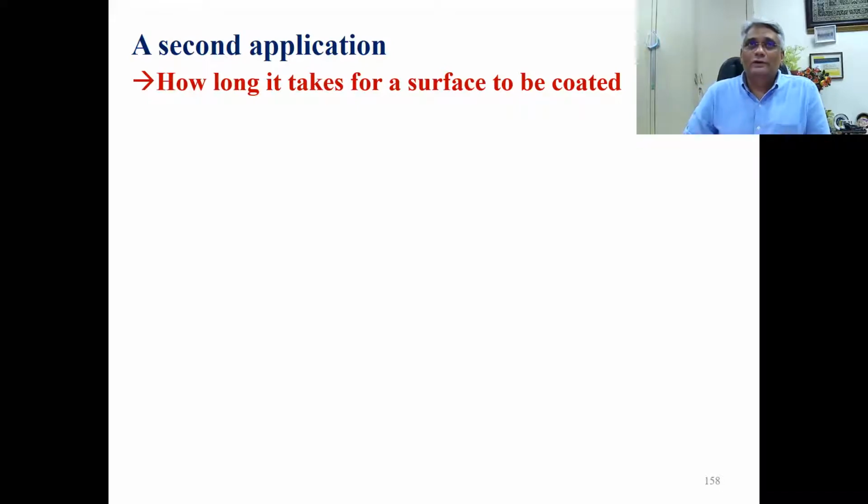But what you need to know is, even if you think you've cleaned the surface, how long it takes for a surface to be coated. Coated in the sense that it need not be a coating during the thin film growth process, even otherwise. What I mean by coating is contamination. If you think it's a clean surface but you leave it outside, a macroscopic examination might make it look clean. But then you do a microscopic examination, you use a lens, and you see the dust molecules present there. There are all kinds of dust molecules, and gas molecules can contaminate the surface.